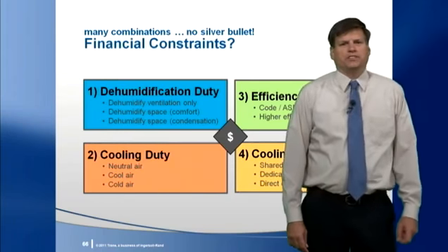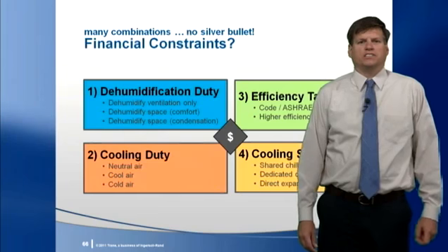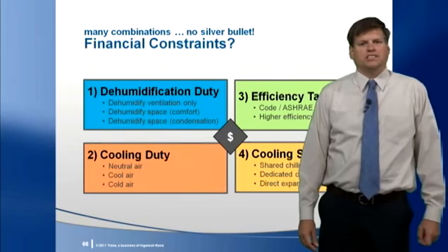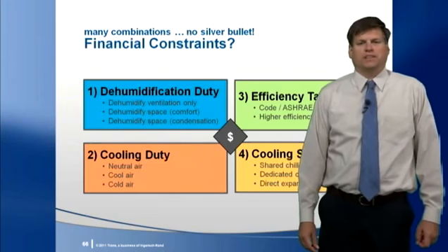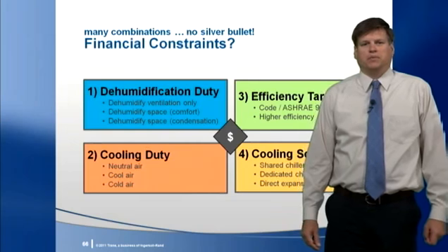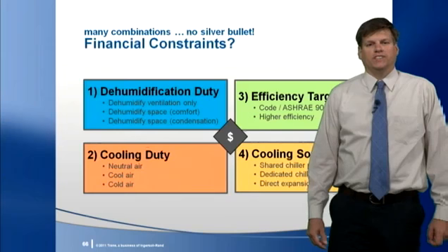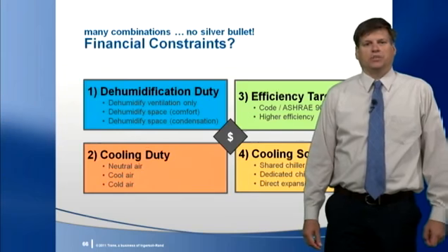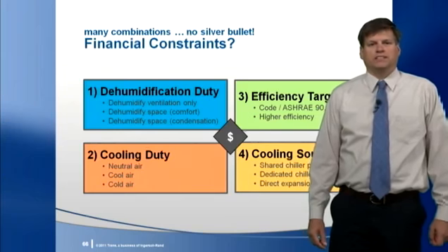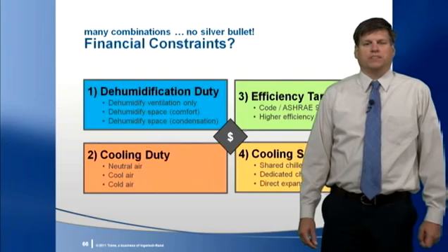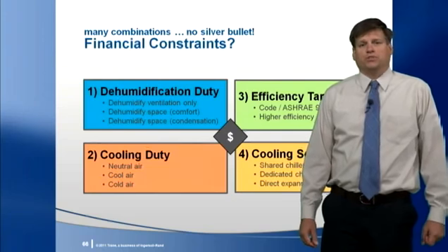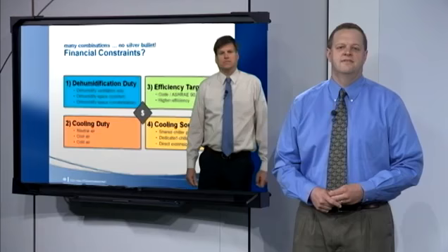The most important factor in this is to consider the various costs of the entire system, not just a dedicated outdoor air unit by itself. A more expensive dedicated unit may allow for the lowest overall system installed cost. And vice versa, the lowest cost dedicated outdoor air unit may result in the highest system installed cost. This relationship can also be true for lifelong operating costs.